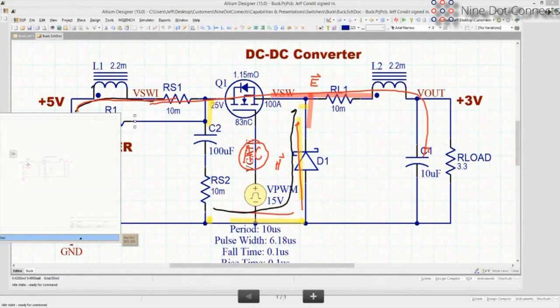In other words, if you just watch this on a transient basis, the current is kind of always flowing into the capacitor, but the net flow through C2 is never going to be a DC. When Q1 turns on and takes a slug of current out of C2, it's probably going to droop a little bit because L1 is keeping the current fairly constant on the input.